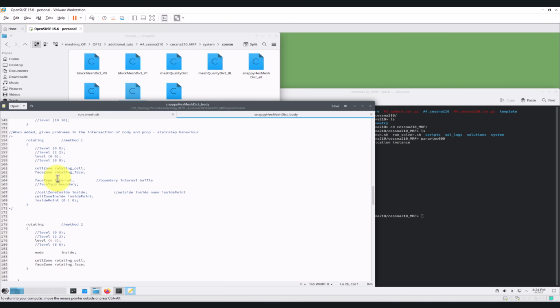So to create that cell region, there are, let's say, two methods. So you have this one that I commented. Usually this method, you use it when you want to create buffers. So you have here three options, and actually it can be internal, buffer, or boundary. Internal will mean internal cells, that's what we want to do for MRF, okay?